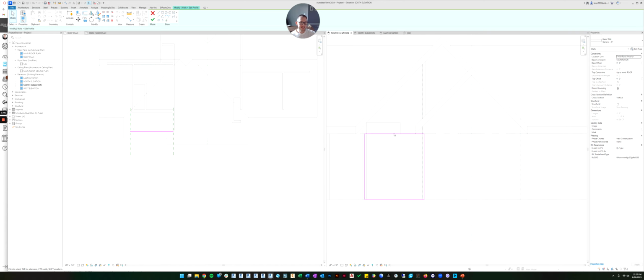So we can edit this sketch to be whatever we want. What we're going to do is extend it so that it follows the roof and fills in this little hole that it wasn't filling in before. My favorite way to make these lines is a little tool up here in the draw menu. We mostly have been using line or the rectangle. There's a little option called pick lines. If you click that, it allows you to pick edges of the model in order to create a sketch.